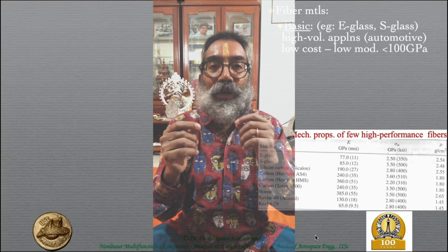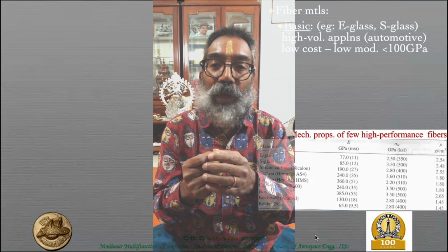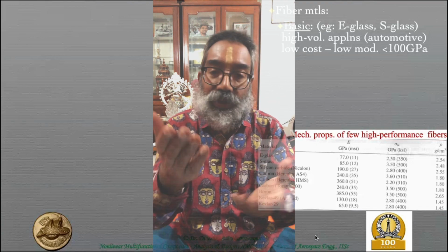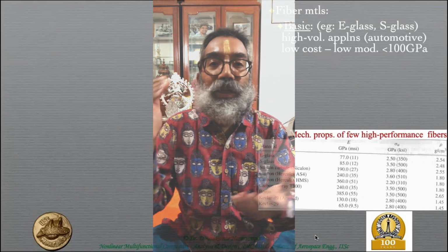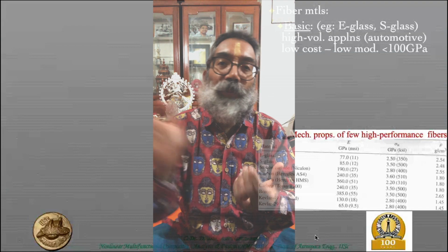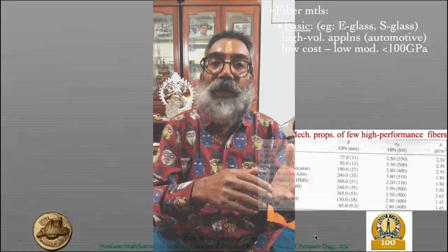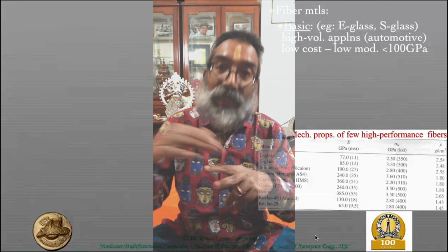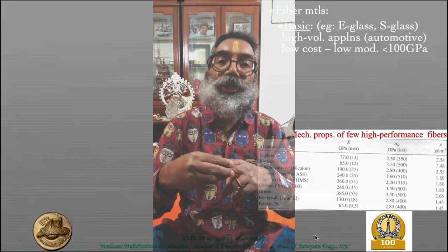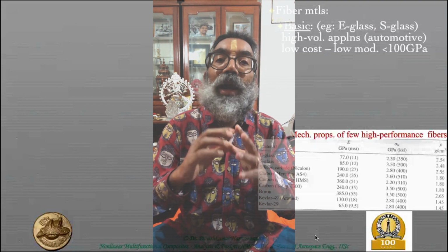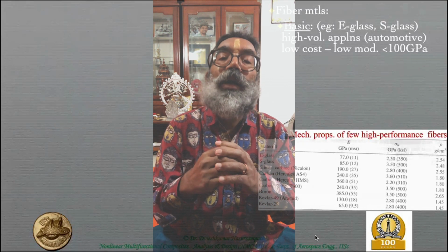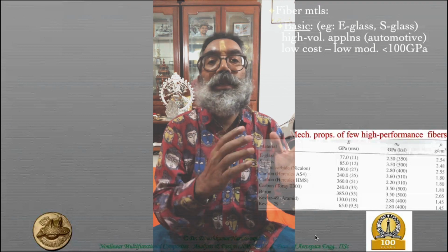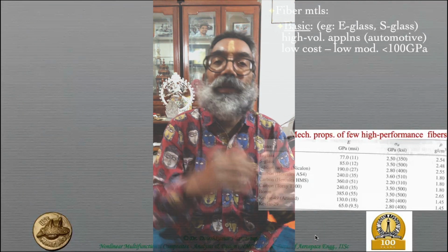We have to understand, if we really want to understand the damage mechanics and come up with a failure criteria like what you're talking about, whether it's Tresca or von Mises for metals, if you want to arrive at that here, there is a lot of thought which needs to be given to the behavior of the fiber, behavior of the matrix independently, and then as a combination along with the interface, and understand the physics that is going on. Still, a lot of empirics is involved in terms of the testing and getting the testing data.